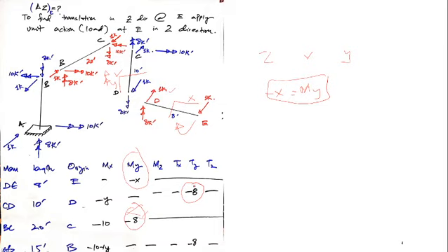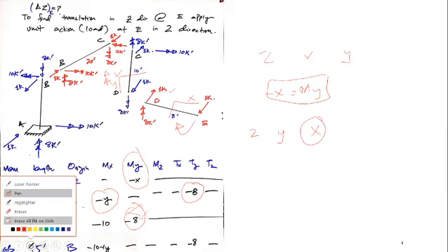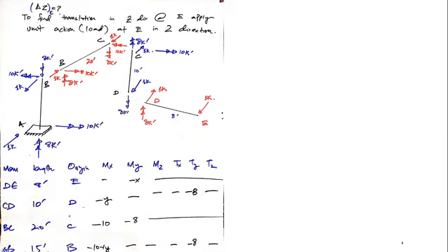This, minus 8. This 1 kip-foot is forming a clockwise moment here. 1 kip-foot is in Z direction. This is in Y. So it would form a moment in X direction. It's forming a clockwise. Resistive would be anti-clockwise. The magnitude would be 1 into Y. That's why I have a minus Y, a moment in the X direction. Next, the member BC and the origin is C.